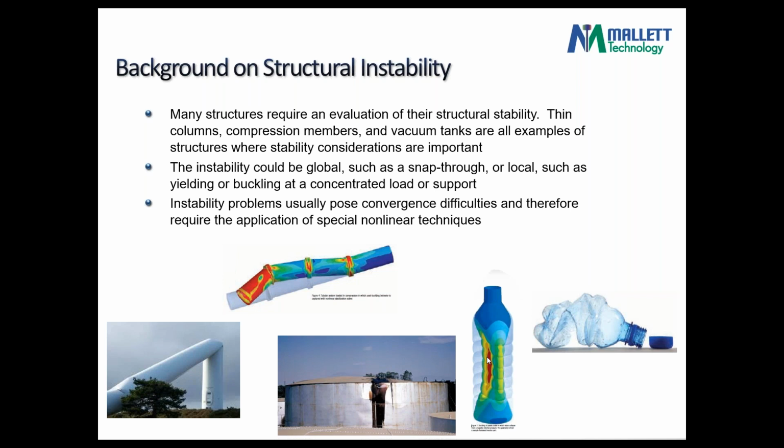These problems can be local or global. You could have local instability because of maybe local plasticity, or maybe the whole structure will collapse. They are a big challenge for us in the consulting and engineering world when we try to model them. You see them in the form of convergence difficulties in your solver. It just doesn't converge if you go blindly and solve it. And the key is really to predict where it is happening, how, and then tackle it.